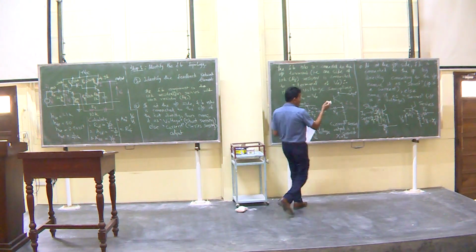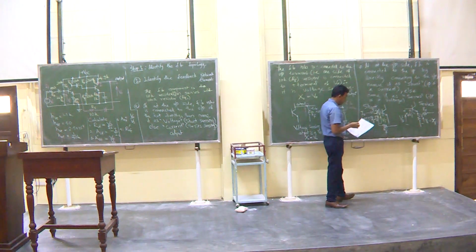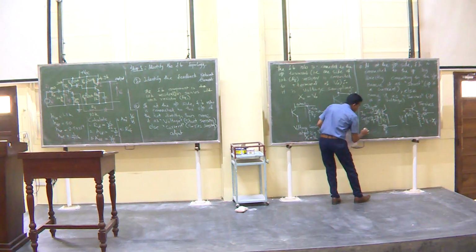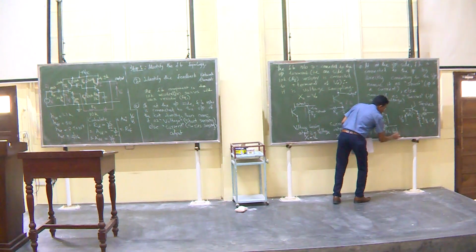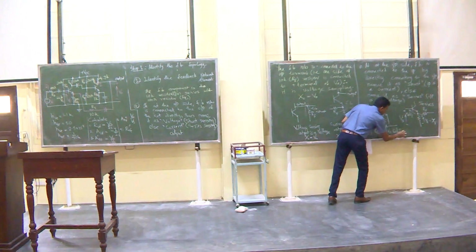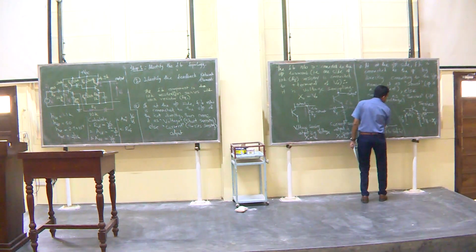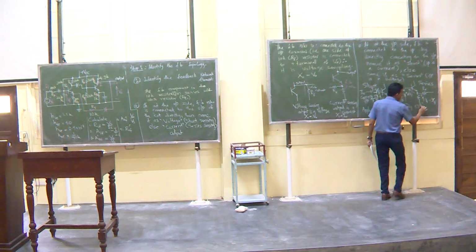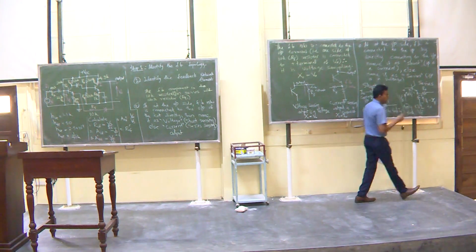If you have this topology, all you need to do is at the input you have to apply Kirchhoff's current law to find I f, I in. Apply KCL to find I in. Whereas here you have to apply Kirchhoff's voltage law to find the input voltage V i.